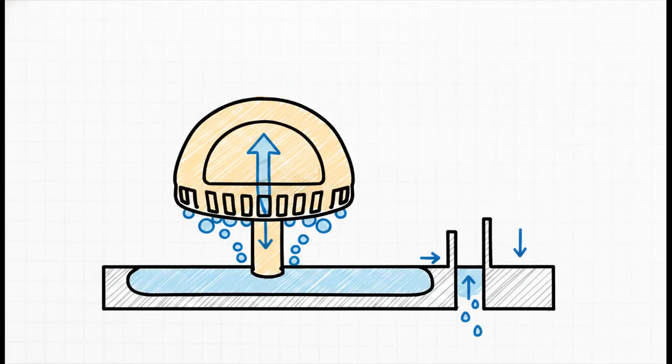And I gotta say, the specific mechanism of bubble cap trays is just fascinating engineering. The vapor doesn't just casually drift through a simple hole. No, it rises up through tiny risers into a cap, and then it's forcefully pushed out through slots as tiny bubbles directly into the surrounding liquid pool on the tray. Then that liquid flows over a weir and down a downcomer to the next tray below. It's literally a highly controlled, cascading waterfall of chemical reactions.